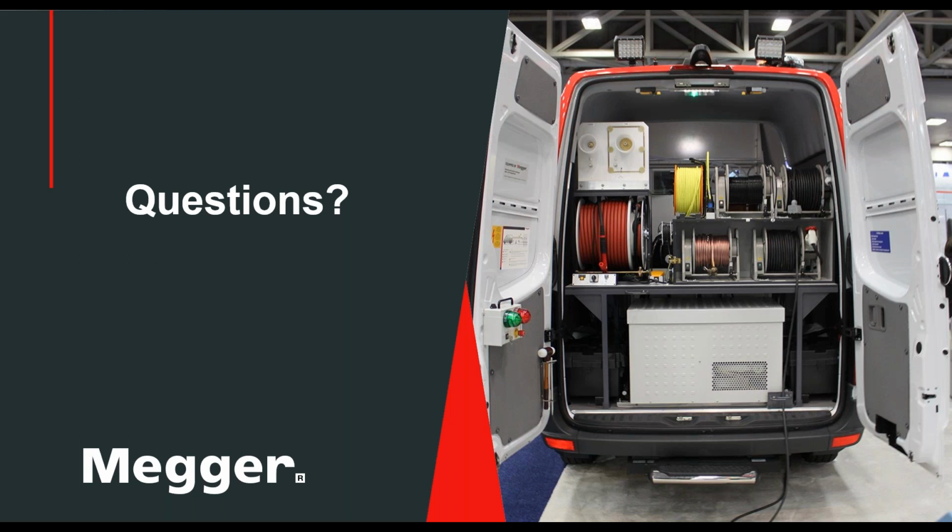All right, thank you. So, Sergio, is the elbow jumper shielded or does it have a wire ground? Let's see. The elbow itself has an unshielded portion on the lead just before the elbow boot itself. If you have the high voltage lead, there will actually be a small lightning bolt laminated picture on that section so that you know in between here and here is unshielded. And then the ground itself is on the high voltage return as well. So it's all intertwined together. Hope that answers that question.